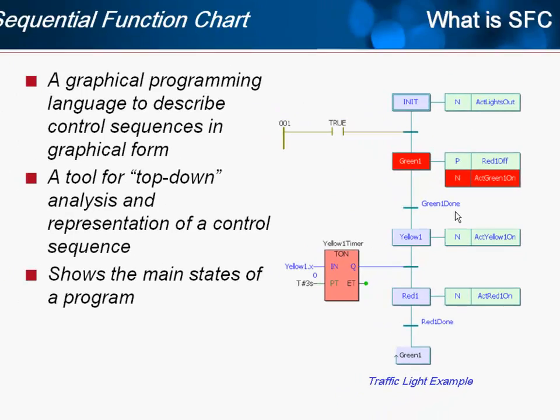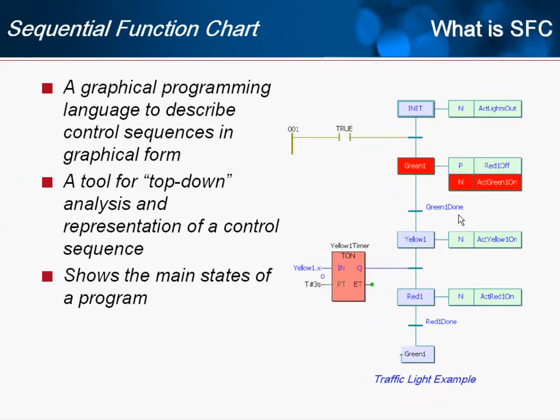And so now take a second to think about how you would program a traffic light using function blocks or structured text or, heaven forbid, ladder. I'm sure you could do it, and probably just as well, but would it be so easy for a technician to just step up and assess the situation if there's some troubleshooting that has to take place? And would your code be this well organized? I think in many cases the answer is probably not. So this is the power of SFC.